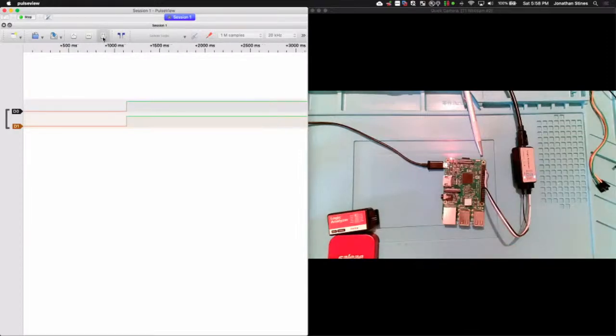Then we can click this button here, which makes us keep up with the timing of the actual logic analysis that's taking place. We'll see some spikes in voltages as things happen. Again, this is over UART, so think of the TTY connection over some type of serial or SSH interface. Imagine just the boot up of a Raspberry Pi. It's going to do its thing, and then at the end, it's going to prompt for a Raspberry login. We'll stop it now that we're getting closer towards the end here. Yeah, that's the last one.